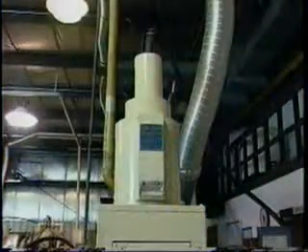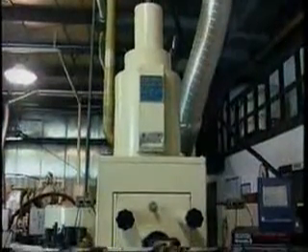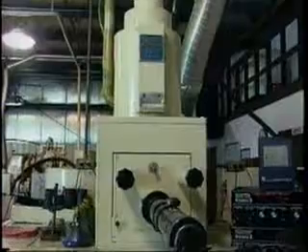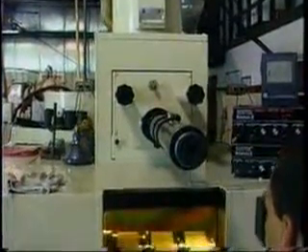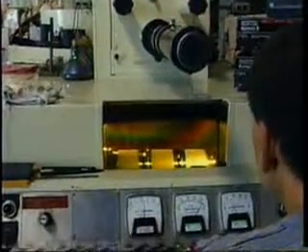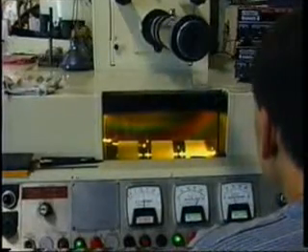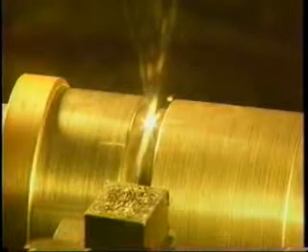In electron beam welding, the coalescence heat is generated by the kinetic energy of a focused stream of electrons directed upon the joint. The electrons are produced by an electron gun, accelerated to high velocity, shaped into a beam by electrical fields, and then further collimated, or made parallel, and focused by an electromagnetic lens. This electron stream is developed in high vacuum, but actual welding can be performed in either high vacuum, partial vacuum,